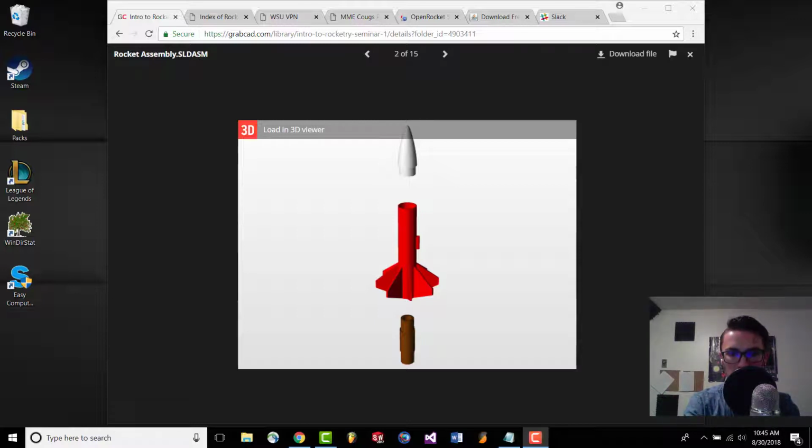Through this project together, we're going to give you a little overview. You can take a model I created in SolidWorks, tweak some parameters, and then we use a program called OpenRocket, where you can take the variables you tweak in SolidWorks, input those into OpenRocket, and then you can see what the predicted flight performance of your rocket is. And actually get pretty close.